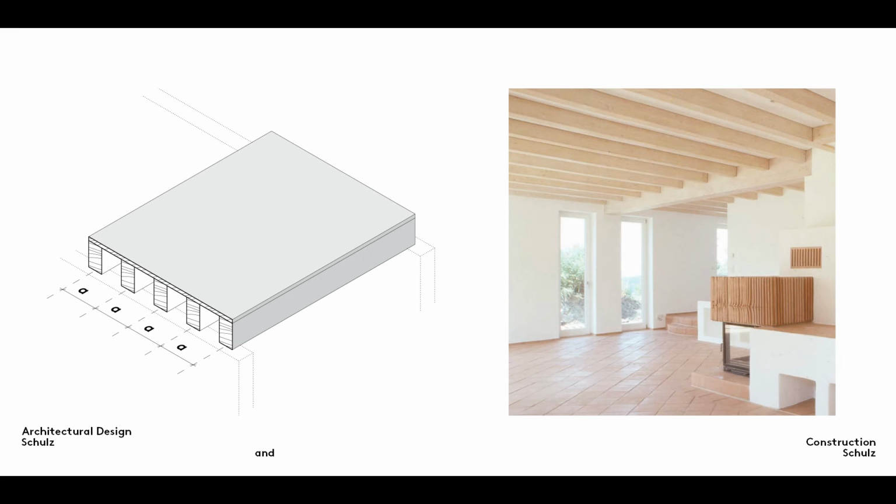Glued laminated timber is produced industrially by gluing together in layers solid timber cut from trees. The bonding together of these layers creates an engineered product that exhibits the properties of solid wood at much greater dimensions. In the first house that my brother and I built in 1994, the floors were made of glued laminated timber due to the large span widths. This photograph illustrates another fundamental principle of the timber joist floor. The beams are always placed between 60 and 90 centimeters apart from center to center.